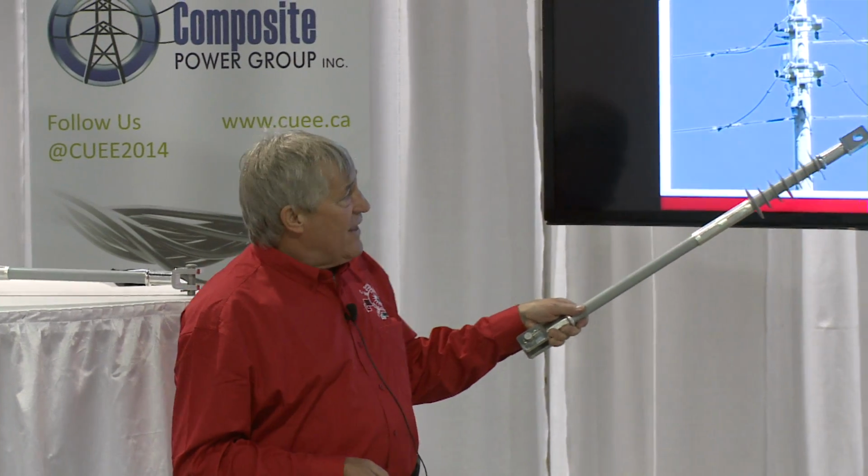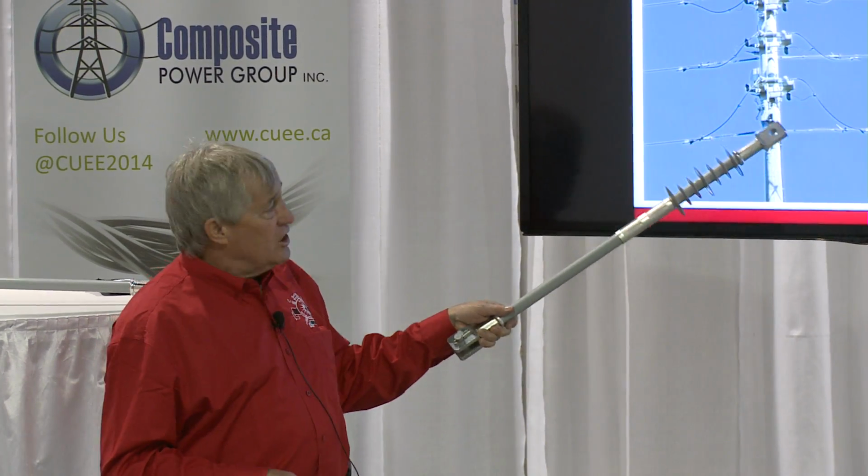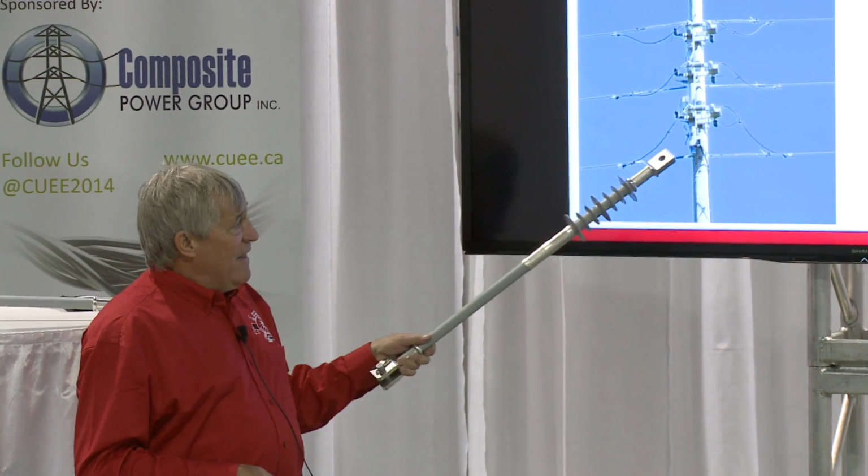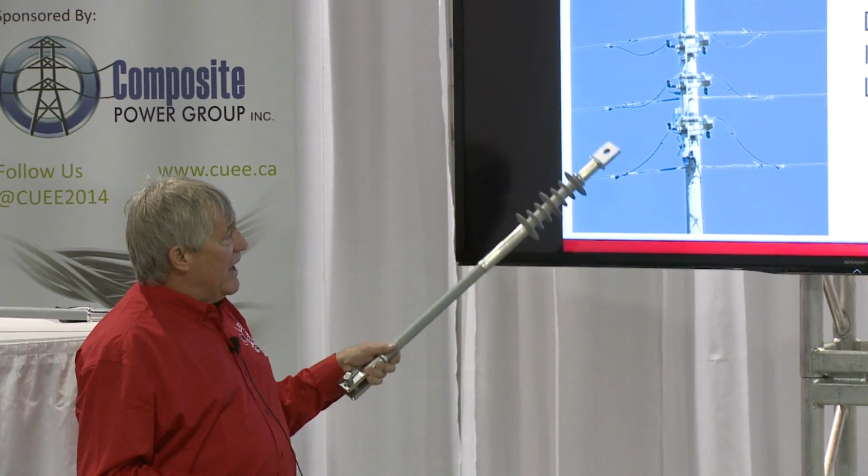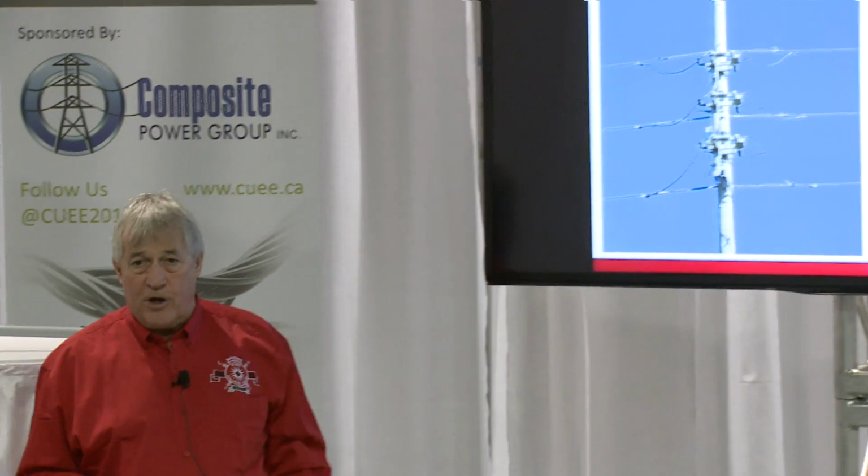Here's a common practice within the utility segment when you're looking to give yourself some additional clearance. In this case, for a load interrupter switch, you want to be able to move the energized point away from the structure, so when the linemen do maintenance on that switch, they can come in there with the switch in the open position, they can lift the loops, and then on each side, up the pole, now they have a fairly large work area to get up there and do their maintenance on that switch gear.